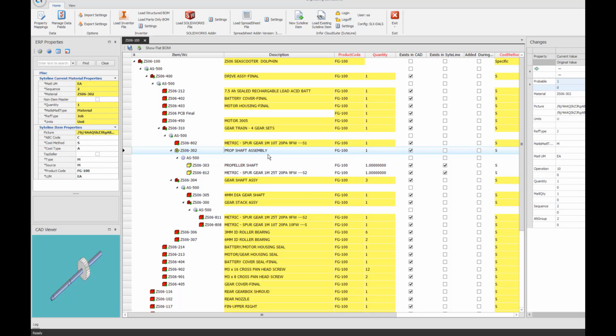So one thing to note is that I didn't save that description back into the model, but it still remembers that the description was that way when I changed it last time. Now, if I wanted to, I could have written that back into the model, and then it would have come in the same way. The configuration of which one drives the data is really up to you. So if you want the data to always be updated from the model into ERP, that's just literally changing the expression for the data coming in.